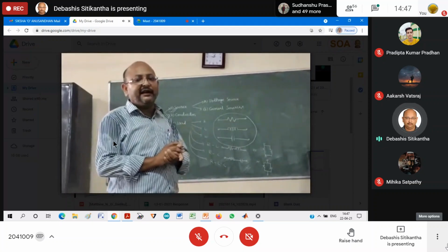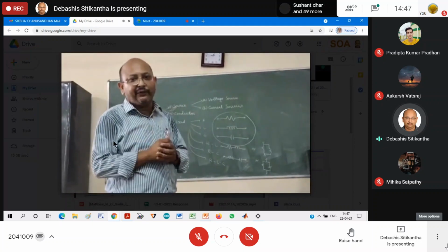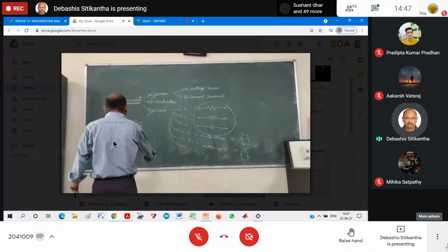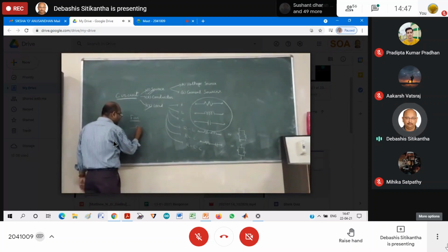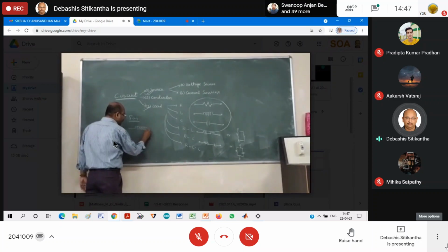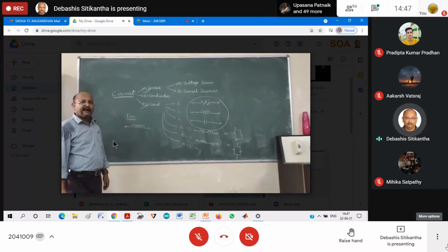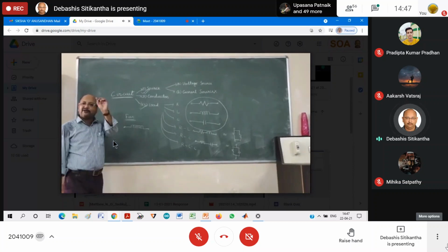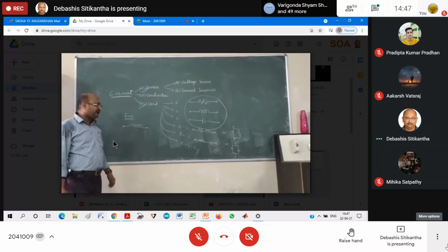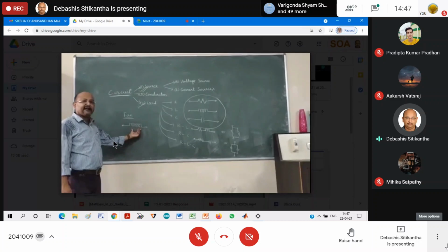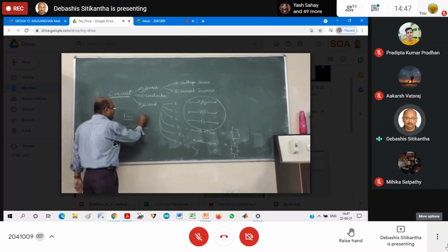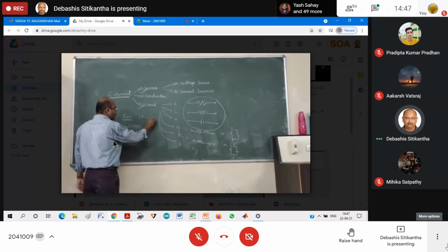It is rather an RL type of load. Suppose I say that this is an inductor, this is a coil. But this inductor is made out of conductors, and every conductor is going to have some sort of resistance inside it. So rather than calling it a pure inductor, I would say it is an RL load. So your fan will come under the category of RL load.